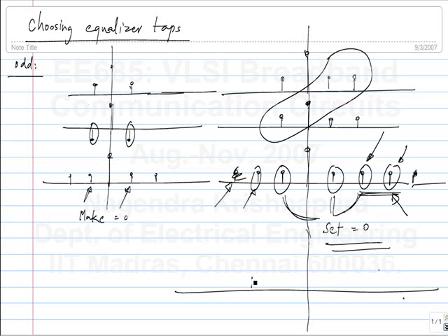With an even number, I think actually as you have more taps, you will have fewer constraints. Right? You have only the number of taps of the equalizer to choose from, and if you choose the number of taps of the equalizer exactly equal to the number of taps in the response, then you will have a limited choice. But still, I think the n taps you cannot make 0 anyhow, and you make the ones closest to the cursor 0. That will leave you with the minimum possible ISI.